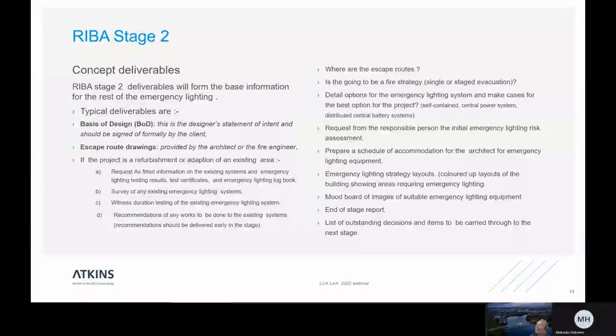It doesn't need to be a detailed drawing. You can give an estimate of the size of the room that is there. I would suggest that you maybe oversize it by 10 or 15% so that you give some kind of remit, because you may not be choosing the final equipment in the end. That may be a contractor decision, but you make sure that the accommodation is representative and appropriate for the project that you've got.